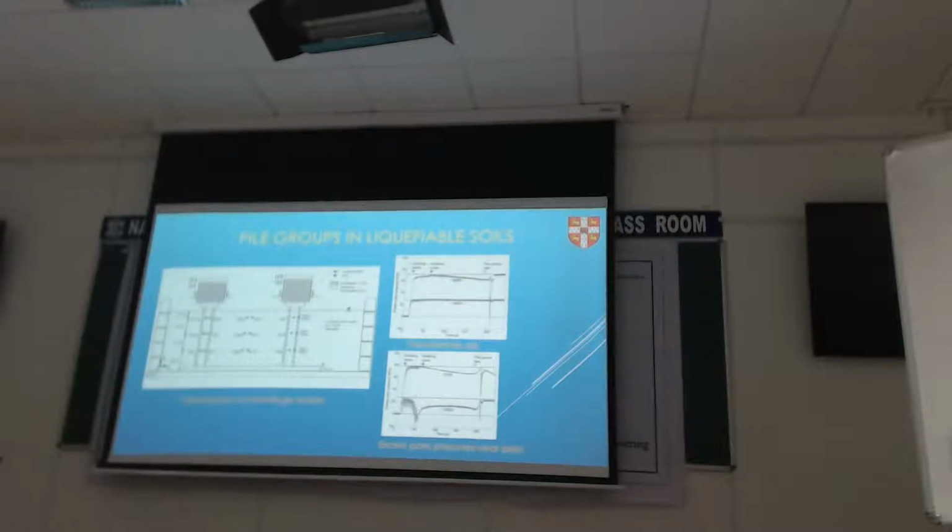Now we know how they are faring. If I look at the pore pressures in the free field, they liquefy. The earthquake is only up to here, and they generate the full pore pressure and stay liquefied. Here is when the pile cap fell and hit the container. There's a shock, and they can measure that also. This is the exact event when the big one fell on, and you can still record the shock coming from that.